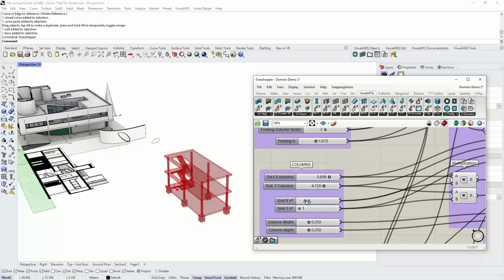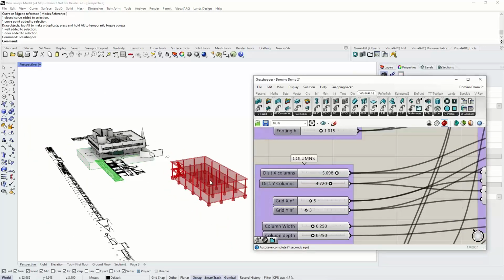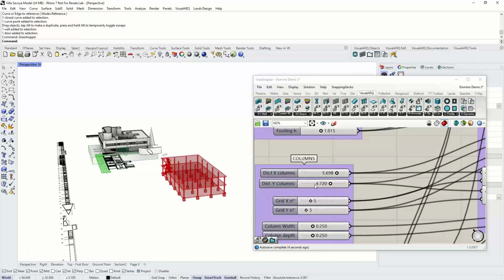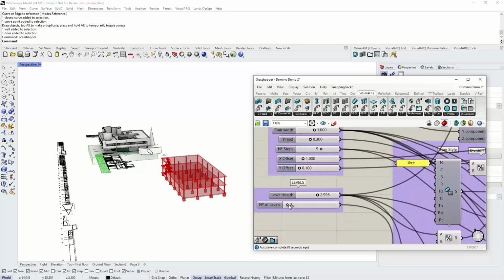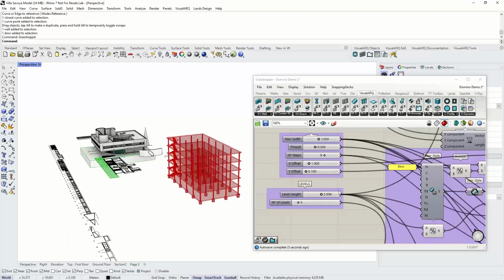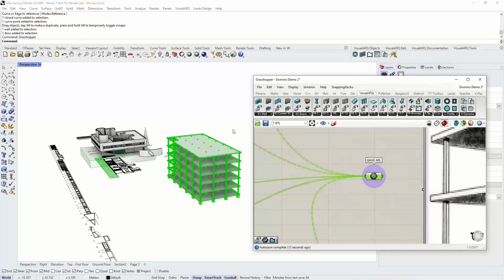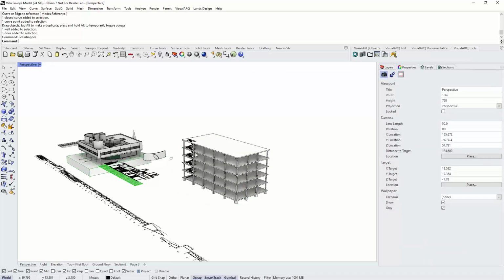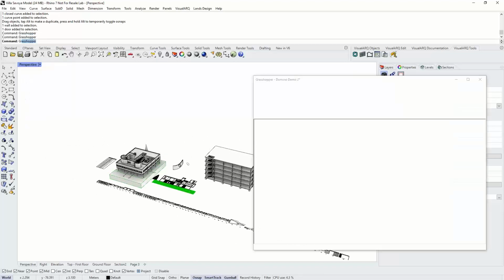So basically, once you have got this definition, you can control the number of rows or columns for this structural grid, and with these commands, we can determine the number of levels and have all this construction modeled very, very quickly. All right, so this is a component that collects all the geometry. After baking them, we'll get here slabs, columns, and stairs.